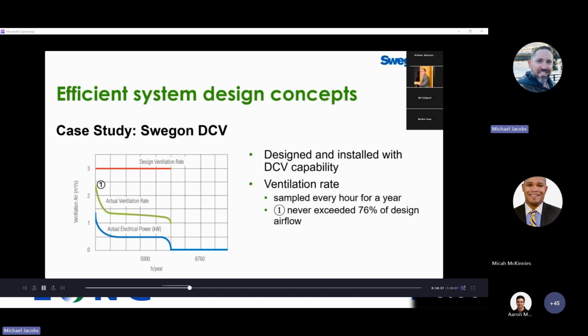But I think there's an argument here that this supports the idea of diversity in variable air volume and DCV systems. And we hear engineers talk about diversity numbers of 80% or 75%. They're saying that although if the building were fully occupied all the time and at maximum load all the time, they would need 100% of the airflow.